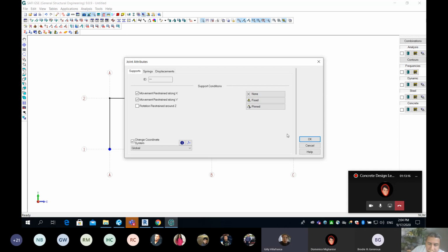I have only one question. Sure, go ahead. In this software, how come it doesn't emphasize the roller? How come it's only bend and fixed? Again, I'm not the designer, but you can do roller here. If I want to make it roller, I'm going to restrain my Y, and I'm going to let it move in the X direction. So you can get the roller from this side. I know it's not pre-set up, but I'm not the designer, so I don't know why this was the choice.